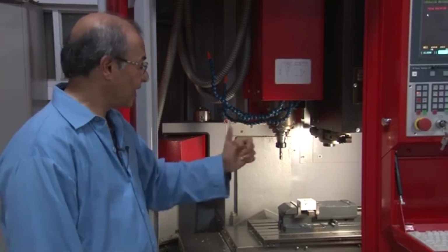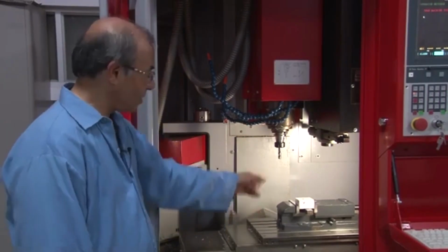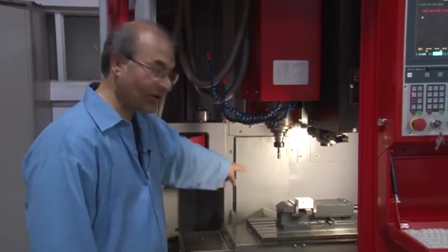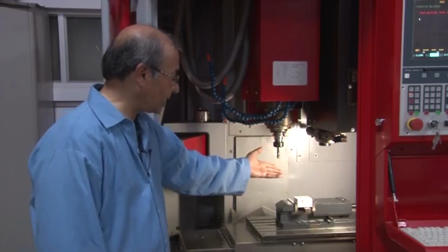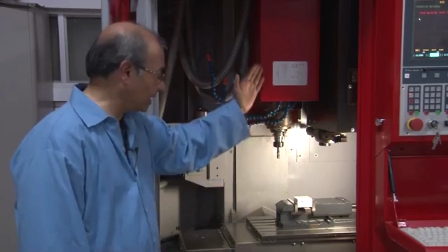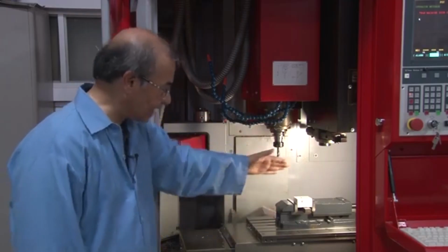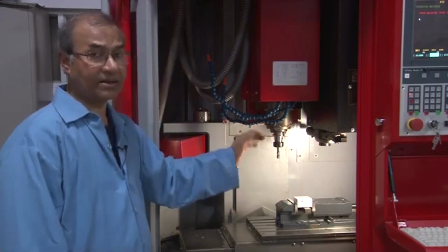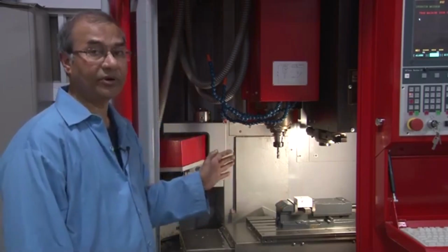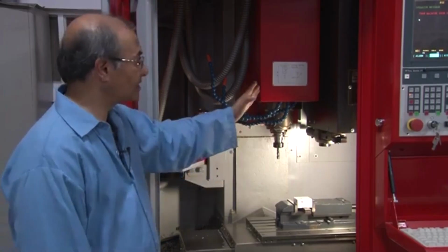And in this machine the XYZ coordinates are different than the coordinates that we have shown you in the turning. Here the X is this movement along the X axis, Y axis is the cross movement, and the Z axis is the lowering and the lifting of the tool, meaning that this is the actual Z axis. So, here is the Z axis, here is the X axis, and here is the Y axis. This is the axis system for the CNC milling machine. All milling machines will have the same axis.